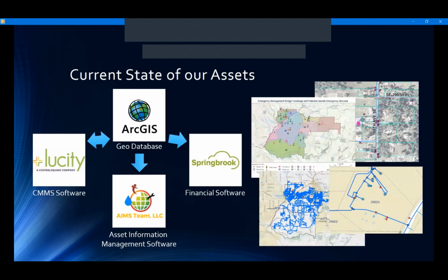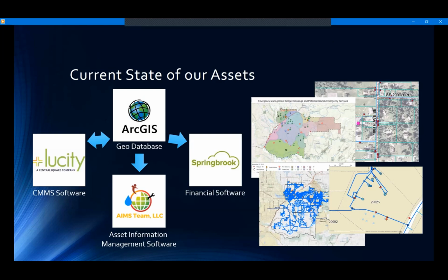So we're utilizing ArcGIS as our geographical information system, so we could begin using maps, analyzing mapped information, and managing geographical information in our database. But what we quickly learned is how important QA/QC of our data was as it came in. And this is an important note for anyone beginning the development of their asset register: ensure that you document processes and procedures for data collection, QA/QC, and ultimately the entire data cycle.